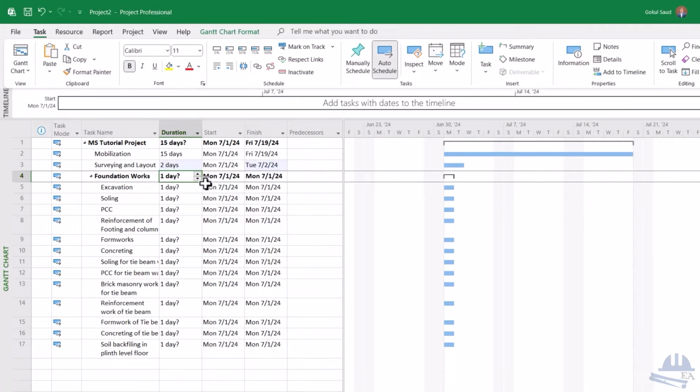And once you are done with it, and once the engineer in charge has verified it, after that you can start the excavation. So excavation work depends upon the depth of the excavation. Sometimes it's just the foundation depth, that is 1.5 meters, and sometimes you have to do some ground clearance also. And you have to estimate how the excavation will be done, whether extra excavation is needed or not, how is the terrain, whether there are more stones or it is just the soil and gravels.